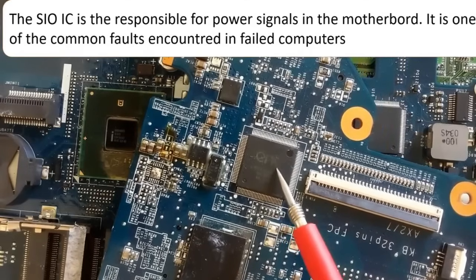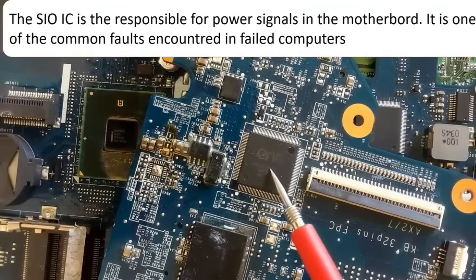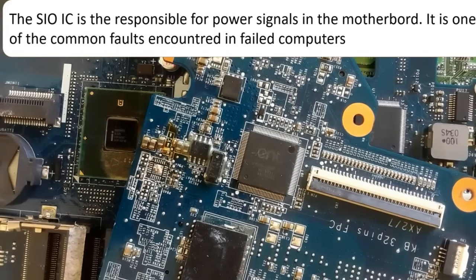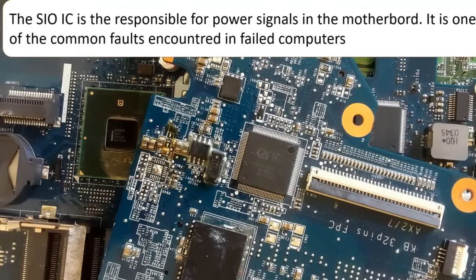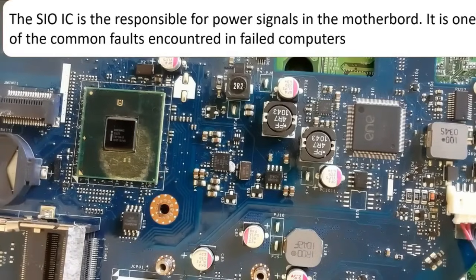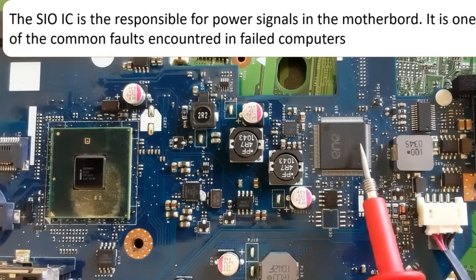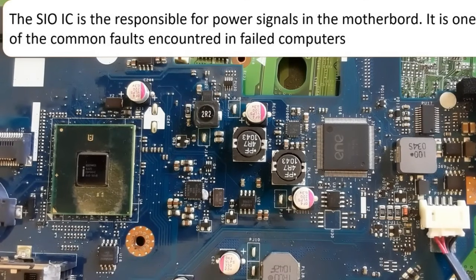Usually you will find in the Super I/O 128 pins, okay? Of course there are many types of Super I/O. There is Winbond, there are many types of Super I/O, or ENE as you see here, okay? But usually the number of pins is 128. As you can see here, the Super I/O is usually next to the ICH.